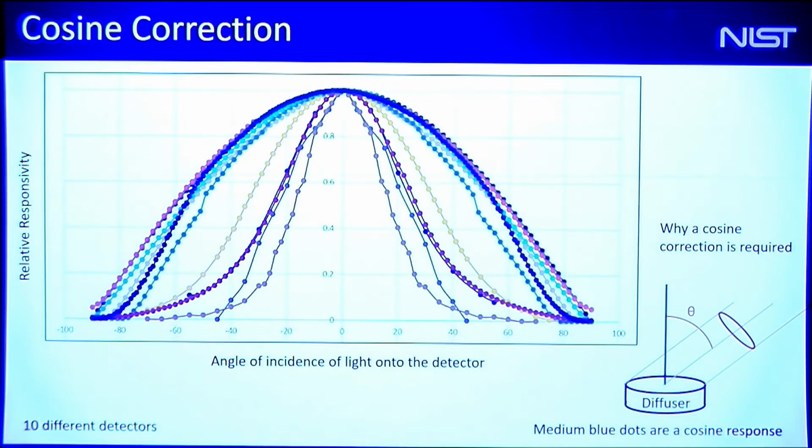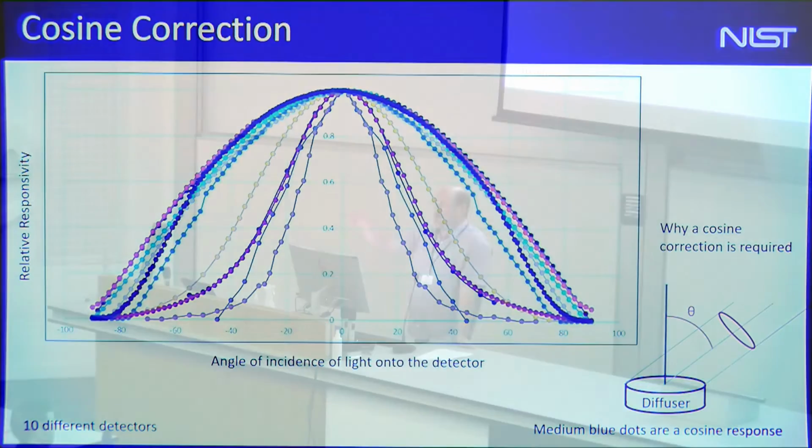In that first example I gave you, there was a lot of what we call cosine correction problem. So when the optical radiation comes in and they radiate something, that's the number of watts falling on a meter squared. When it comes to the device at an angle, it is now extending that projected angle out there that goes by the cosine. So you would expect your detector to have a similar response if you were to take a source that points down and move it over here to 45 degrees. You see the square root of 2 difference.